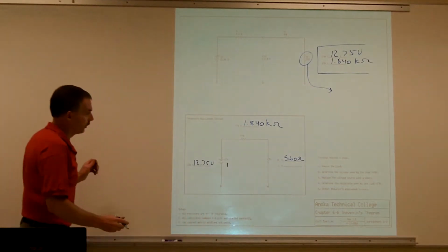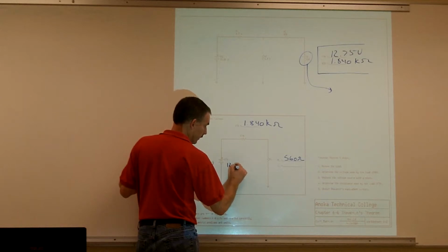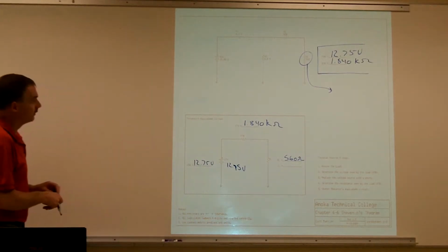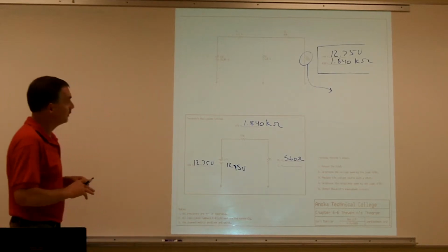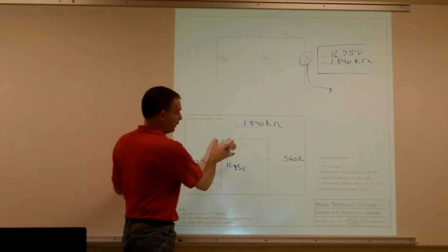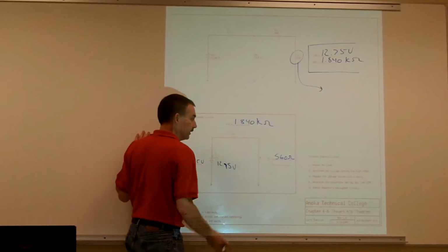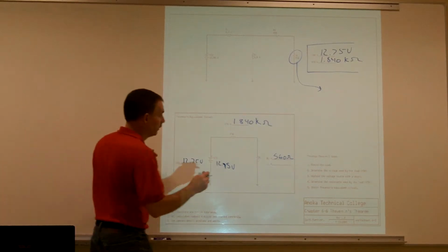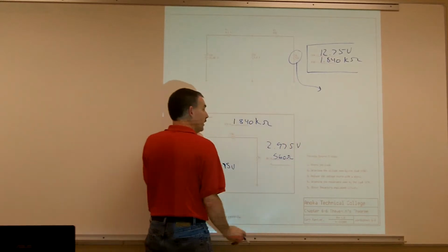So what was the voltage then across the load? You had to find the voltage across the load for calculating out the current, right? So again, you could either go ahead and add them together and divide by the resistance and get the current, or you could just use our voltage divider formula. 2.975 volts. I got it.